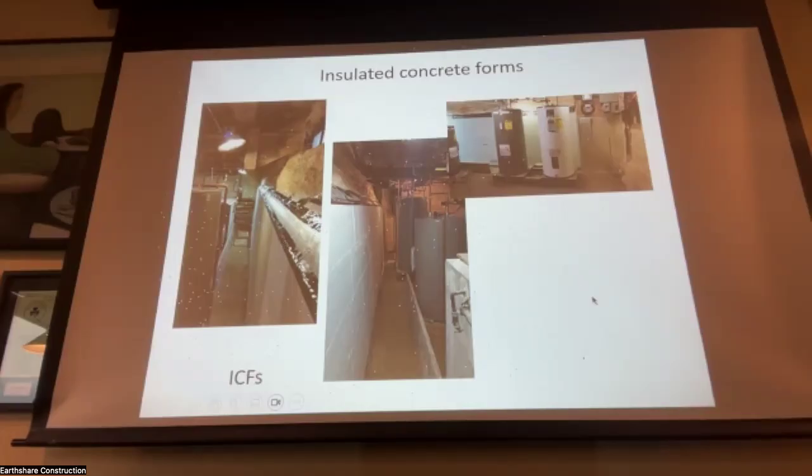This is actually my basement in one of my buildings. And this is a rubble foundation. The problem here was we were getting silt coming in every spring when the water came off the roof, and there would be a lot of water. I put the ICFs in half, braced them into place with counterforts, and injected foam behind the ICFs between the rubble wall and the ICFs.